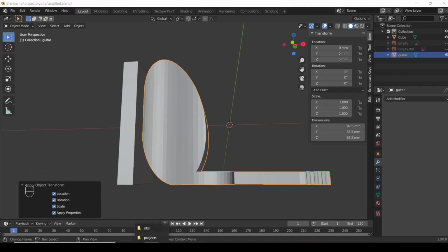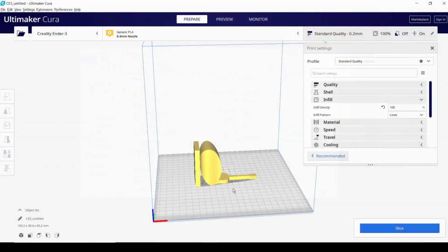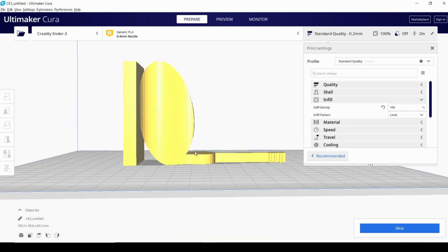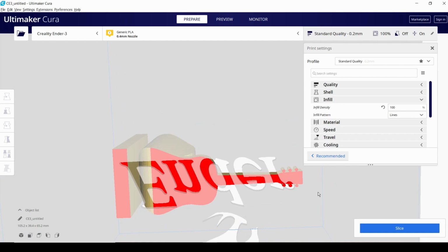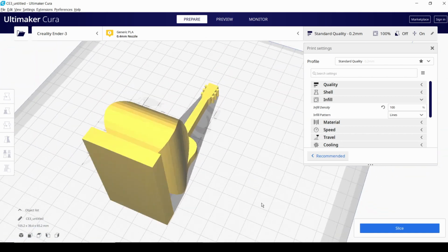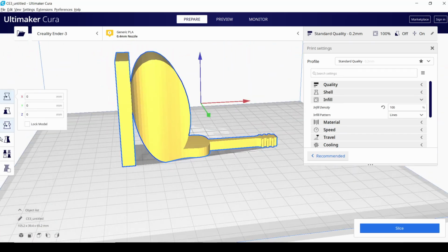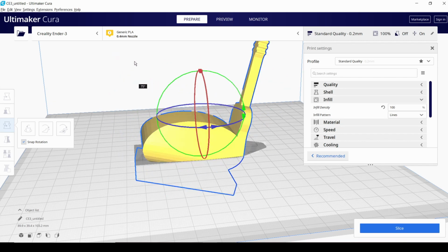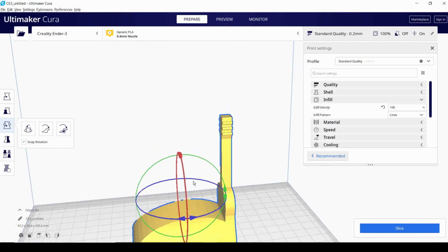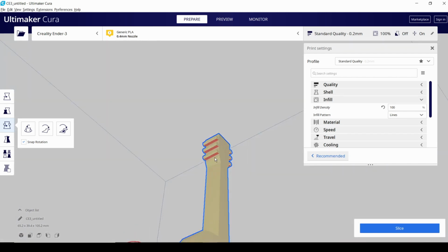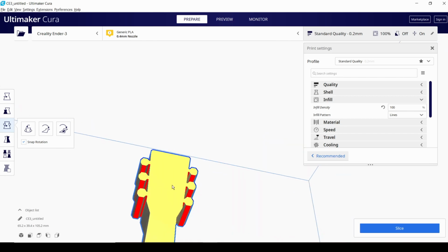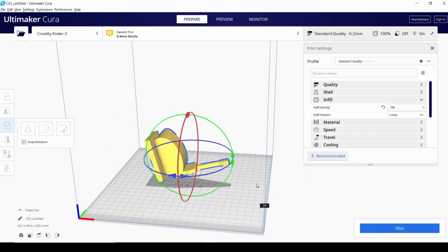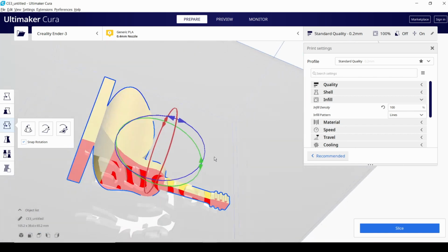Okay. Let's go ahead and open that up. There we go. If I zoom in, what you'll see is the only red spot now is where we're 3D printing. If you select this and rotate it 90 degrees this way to the direction it would have been at, what you'll see is we have red marks underneath. What this means is we need to put supports in to print in this direction. So like I say, the direction we had it is absolutely perfect.